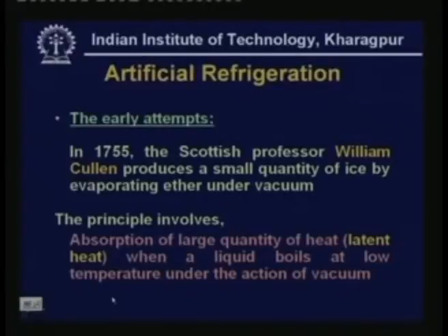You can see that this process is not a spontaneous process because some external effort is required to maintain the vacuum. That means you have to have some vacuum pump, which requires some mechanical energy input, so that continuous vacuum can be maintained in the bell jar. This process is also not very useful in practice because once all the ether evaporates, there won't be any refrigeration. So if you want to make it practical, we have to recycle the ether.